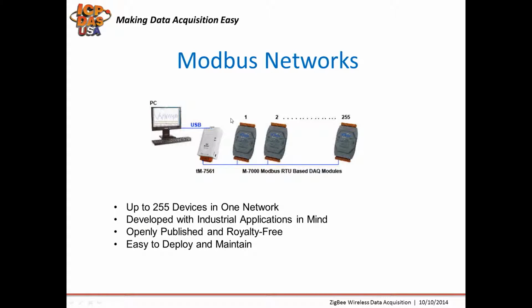Each Modbus device in a network is given a unique address. In serial Modbus RTU networks, only the node assigned as the master may initiate commands. In Ethernet-based Modbus TCP networks, any device can send out a Modbus command. One master device is usually configured to send Modbus commands. A Modbus command contains the unique Modbus address of the destination device. Only the destination device will act on the command, even though others might receive it.